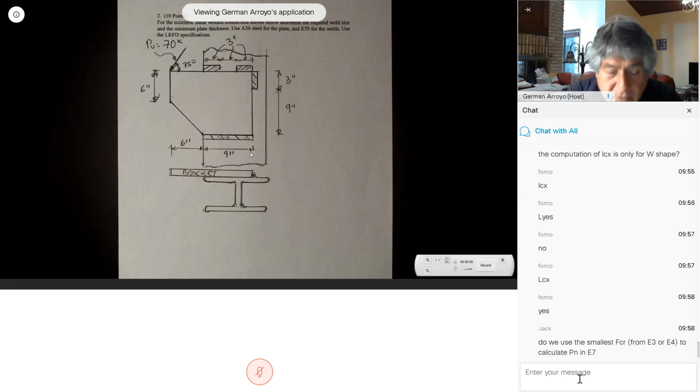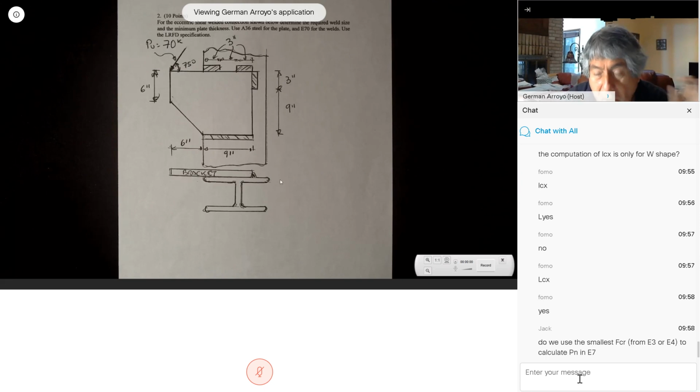The table that I'm giving to you treats the welds as lines. And that's why if you look on the top of the table, it says inches. The polar moment of inertia is inches to the third instead of inches to the fourth. So we represent this with this little rectangle, but in reality, it's a line. A line doesn't have a dimension. But if we use two dimensions, B and H, that's the way we're going to do it. So there is only one bracket. Sometimes there are two of them.